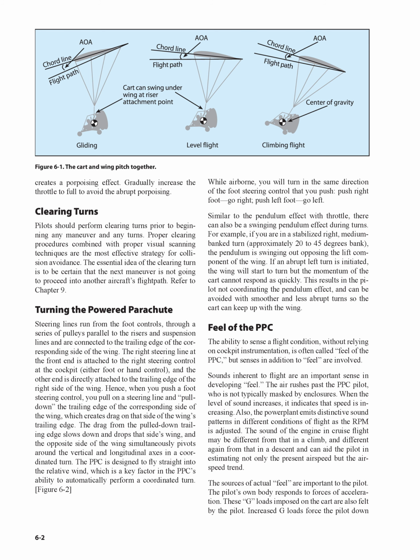Feel of the PPC. The ability to sense a flight condition, without relying on cockpit instrumentation, is often called feel of the PPC, but senses in addition to feel are involved. Sounds inherent to flight are an important sense in developing feel. The air rushes past the PPC pilot, who is not typically masked by enclosures. When the level of sound increases, it indicates that speed is increasing. Also, the power plant emits distinctive sound patterns in different conditions of flight as the RPM is adjusted. The sound of the engine in cruise flight may be different from that in a climb, and different again from that in a descent, and can aid the pilot in estimating not only the present airspeed but the airspeed trend.